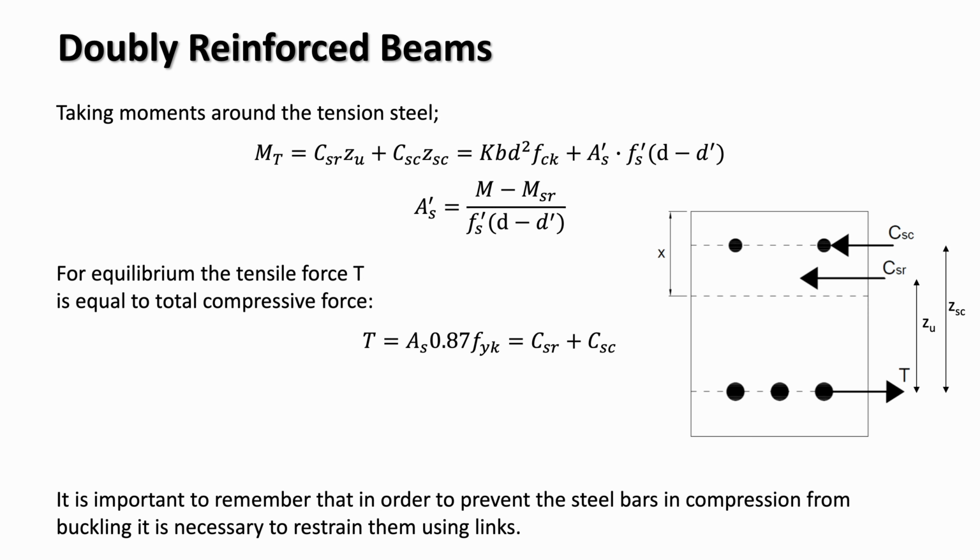Finally, it's important to remember that compression bars must be properly restrained to prevent them from buckling under compression. In practice, this is achieved by tying them to the links. And now, we're ready to solve an example.